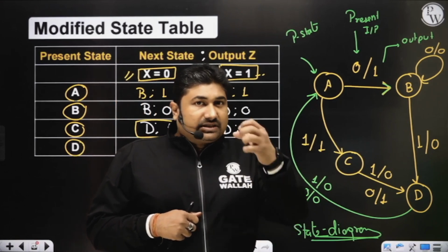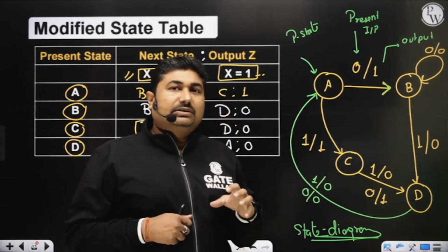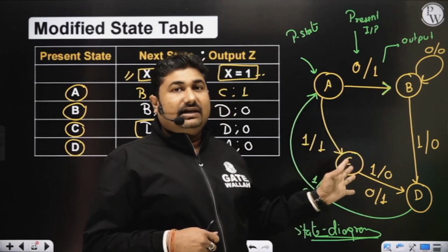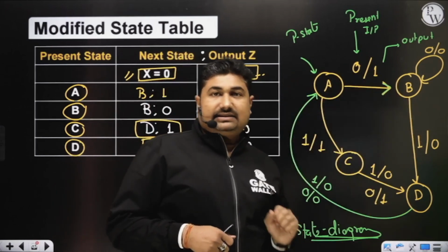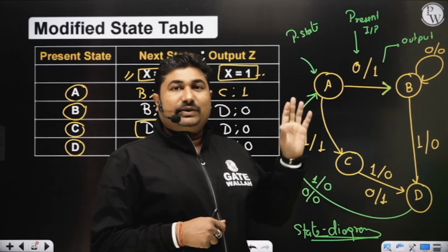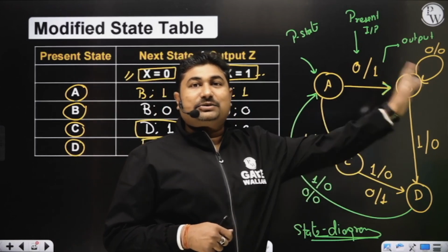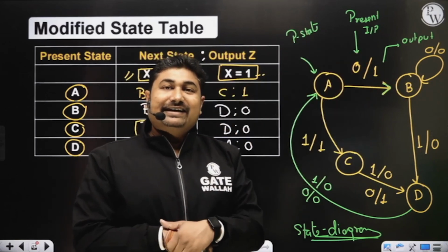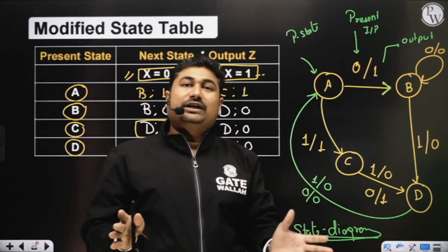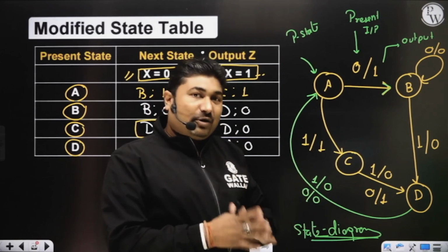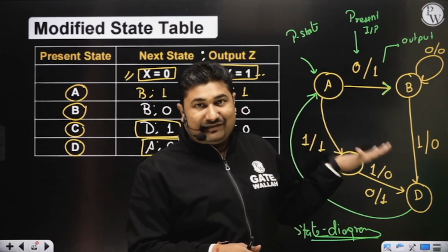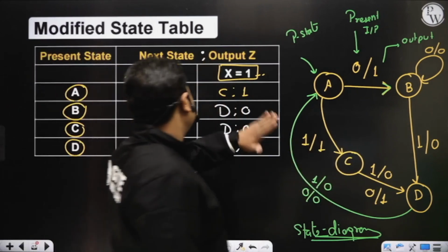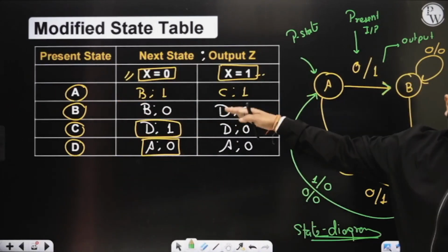Whenever a user first comes to you, he asks about the states first. Like, I want 5 different states. If for input this, the condition goes to this state, else it goes to some other state. In that way, first of all, you need to understand the user's concern, and accordingly you will draw the state diagram first. From the state diagram, you can construct this state table.